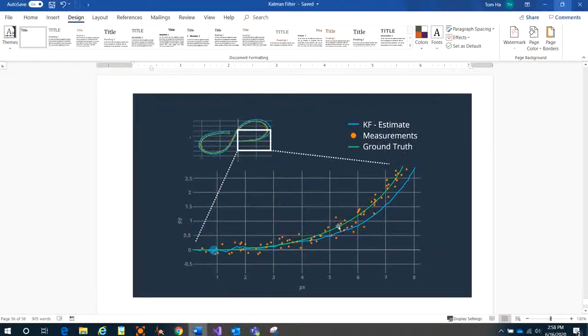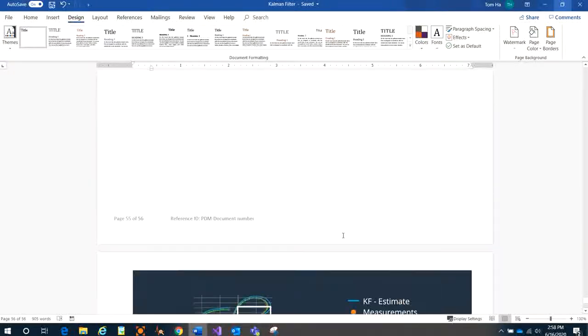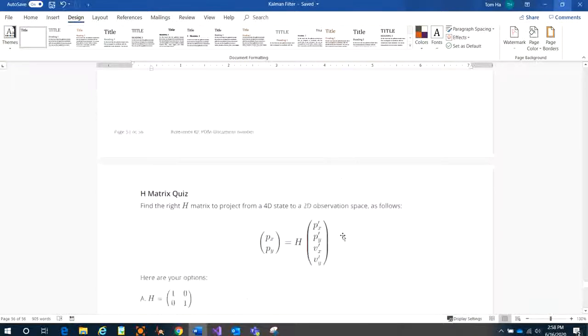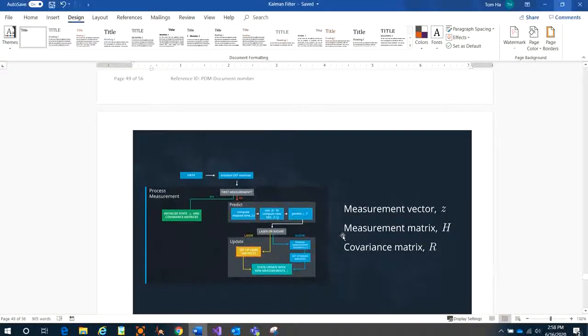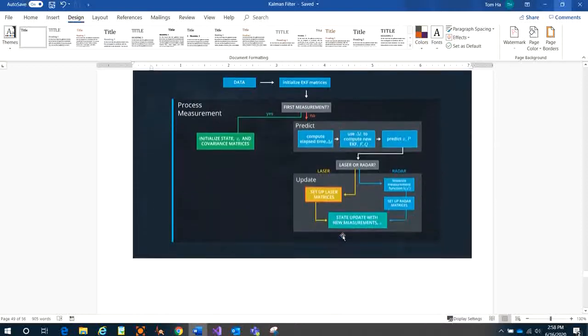That's really cool, right? That's the reason we use sensor fusion. We apply the radar data here, because the radar data gives you polar coordinate values, right? We will talk more about this in the next video. In sensor fusion, you have to combine two steps: the first from the LiDAR sensor, the second from the radar sensor, for the measurement update, to correct the movement of the state of the pedestrian, not only linear motion going straight but maybe circular, right?